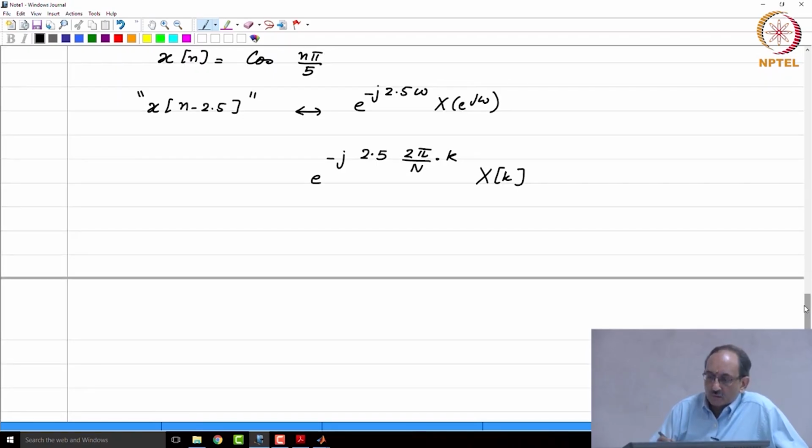And then what we did was we restricted this only to the first half. Remember, we computed this over 20 samples. Therefore, we computed the 20 point DFT, and we applied this only to the upper half of the transform.